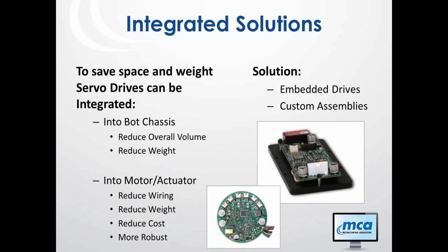And the other upper picture is showing a drive. The black part is actually a side of the manipulator that you would see on a platform. You open 2 screws, unmount it, and you can pull out the drive assembly. So there's a drive and a controller all in one. That's the robot controller for the arm. It's all built in that one assembly. On the outside is, again, just going to be power and communication. So we're integrating assemblies, putting those assemblies inside the bot, reducing our wire count and making a more robust system.